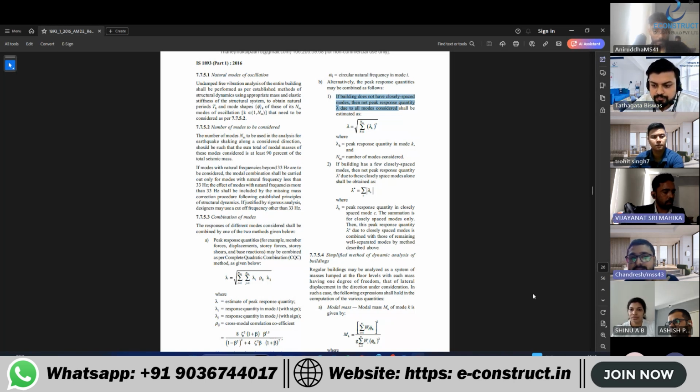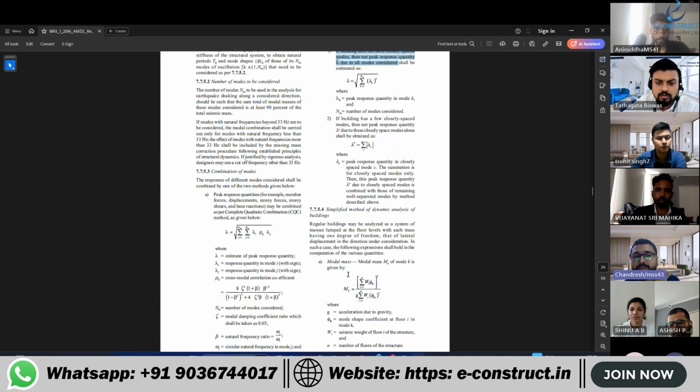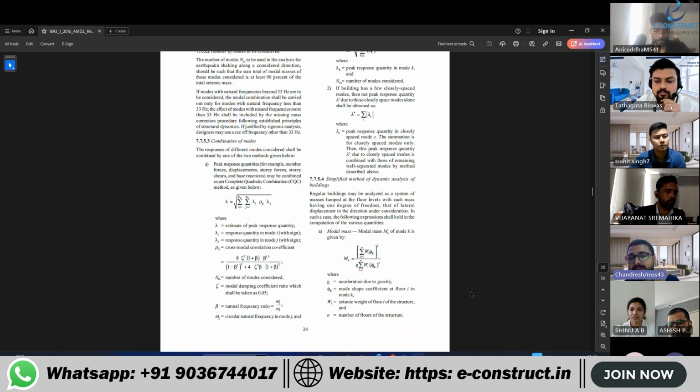Hello, sir. Yes. Sir, can you please explain it once again? Why do we use CQC and SRSS? I don't understand, sir. CQC is used if you want two modes to talk between each other, in a nutshell.